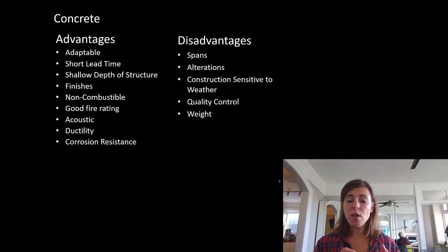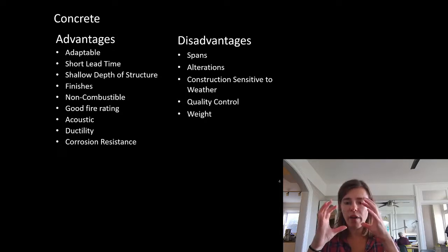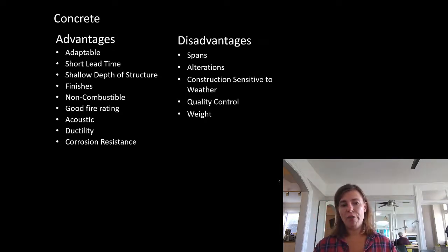Now, steel, when it rusts, expands to 10 times its size. So when you see a big chunk of rust, the amount of material that really was there was only 1/10 of its size. So if you have a big spall of rust that's big, it was just a micro fraction of steel. But when it's embedded in concrete, as that steel rust tries to expand, it pushes outward, and that concrete can start to spall off. So it's still got great corrosion resistance, but it's good to understand where the failings are of it.